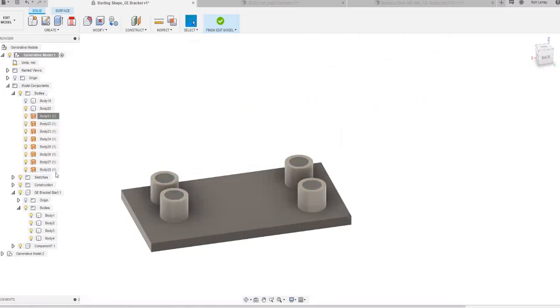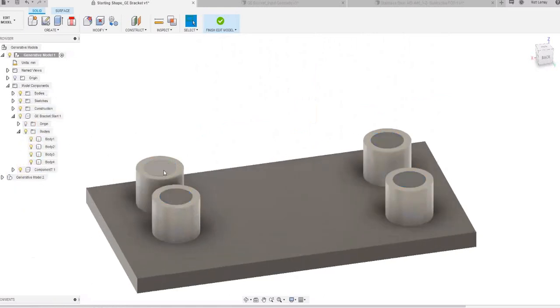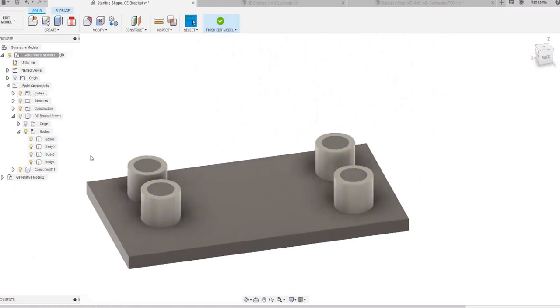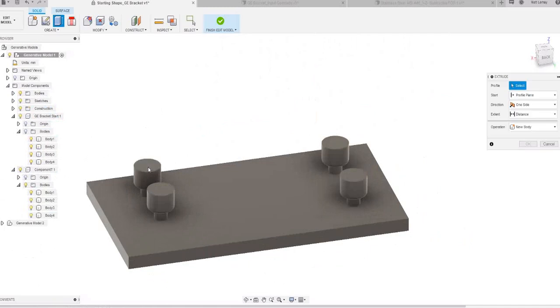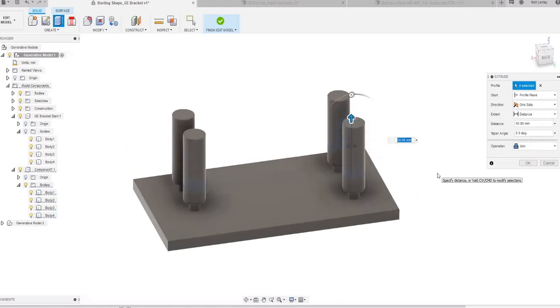So we can't just call out the inside of all of those faces to have a bolt there later on. We also need to know that we have the assembly clearance to reach all of those geometries. So what we could do in this case is just take the top surface from each one of those and extend this up a certain amount, so we know that after we've generated the geometry and we have our solid part, there's nothing blocking the assembly process of actually applying the bolt within those faces.